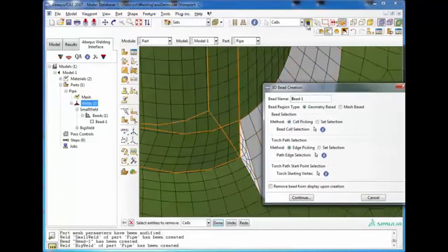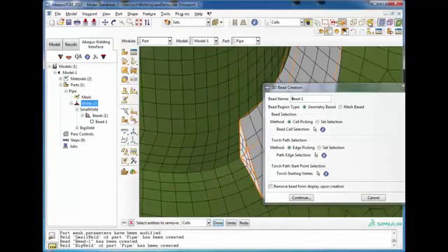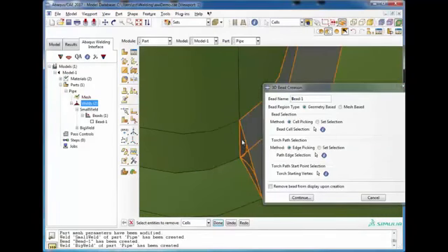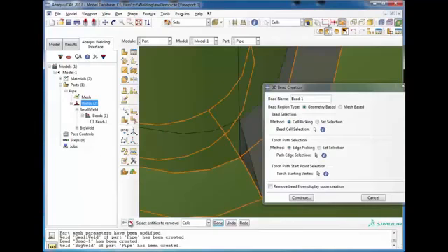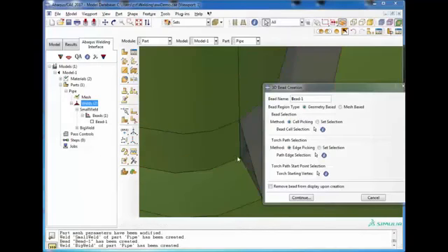Now if we turn off the mesh here, oops, we can see these faces. Let's close this down. You can see these faces. These are just partitions that were created on this one face, just so we can define the 3 different beads in this case. So what I'm going to do is I'll go ahead and define this top bead first.